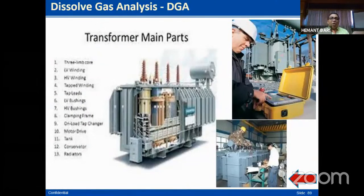And the last one is dissolved gas analysis, that is the DGA. Transformer oil testing. So my transformer oil condition is in what way, or because of the contaminated oil my internal parts may get damaged. So to avoid this, unwanted gas formation is in what concentration, all these question answers can be found out with the help of dissolved gas analysis. So the oil testing plays a vital role and clearly gives an indication whether I should go for a replacement or not.